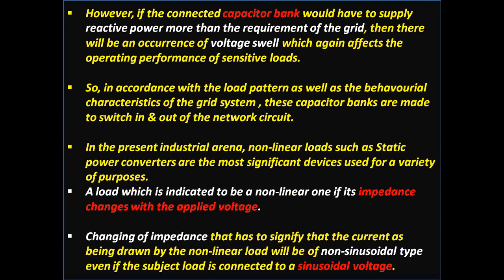However, if the connected capacitor bank supplies more reactive power than the requirement of the grid, then there will be a voltage swell, that is an over voltage, which again affects the operating performance of sensitive loads.